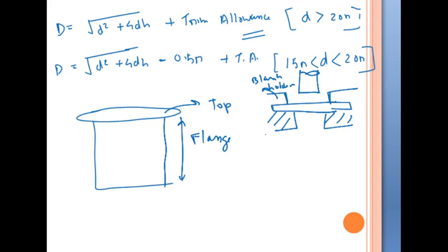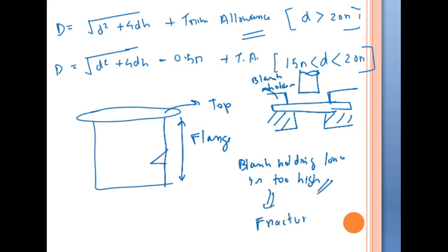Now if the blank holding force is too high, then there will be a fracture in the flange region.